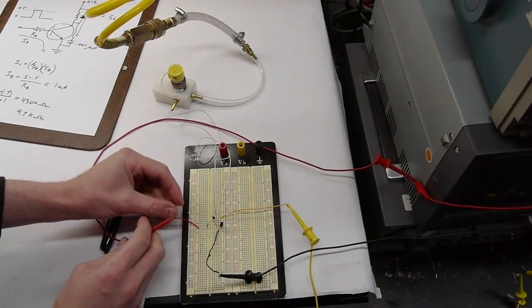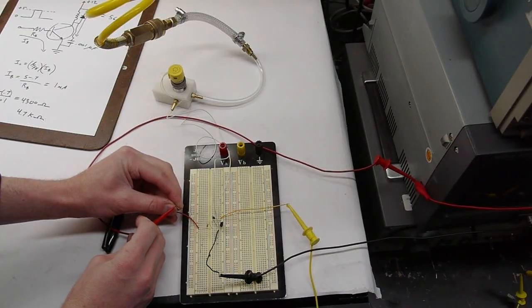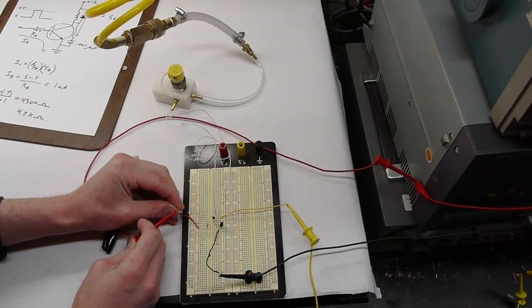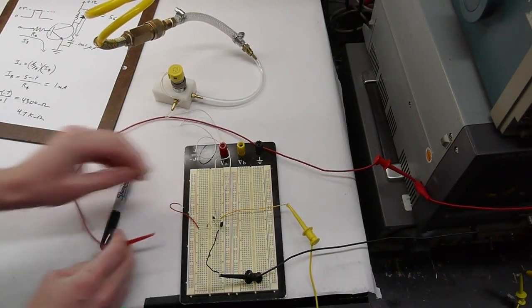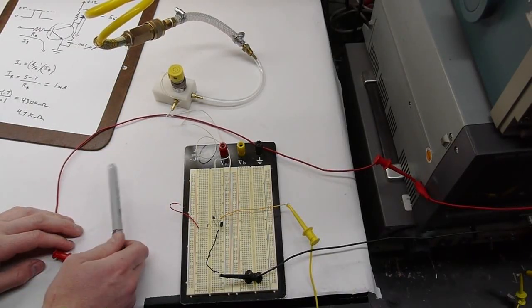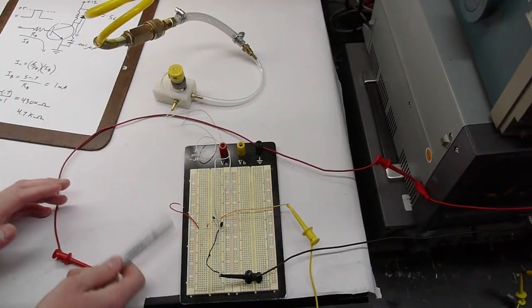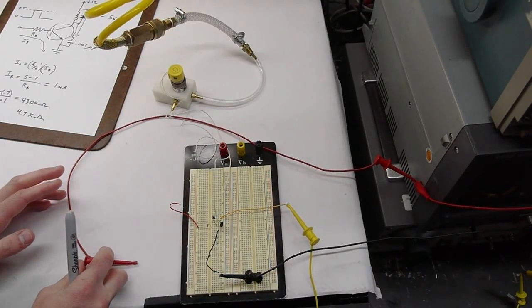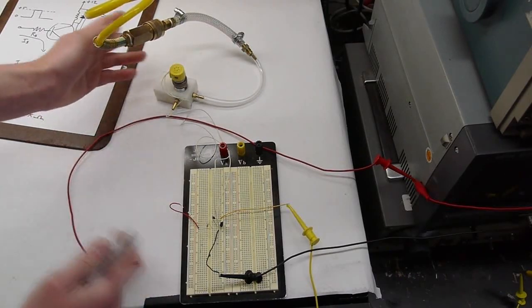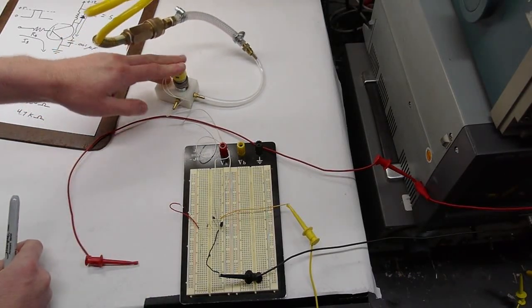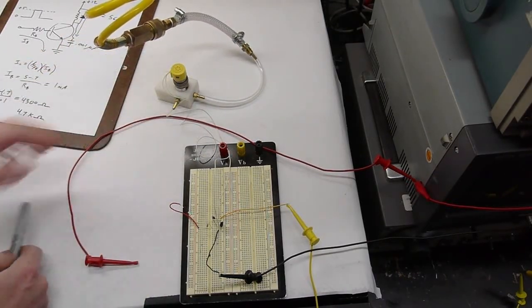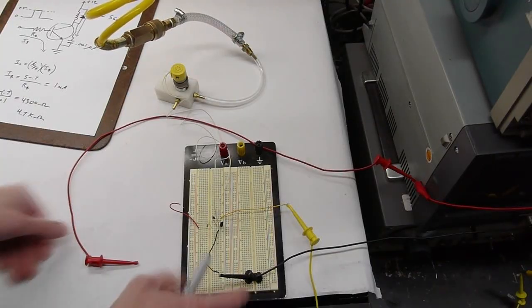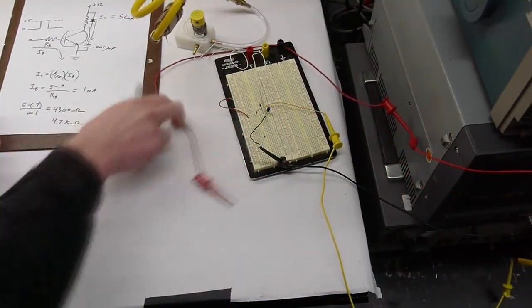So if we put 5 volts into the resistor, control the valve quite nicely. So what we've done here is taken a very, very small signal, 5 volts at 1 milliamp or less, and are able to control, admittedly a pretty small signal, but we've taken care of the inductive kick from the solenoid valve.